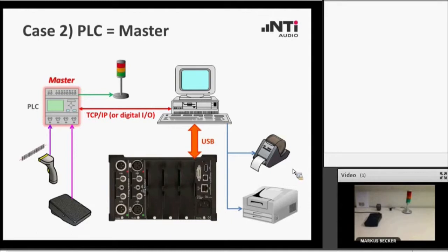The third option is to connect them directly to the auxiliary I/O interface of the FX100. And this applies not only for very simple devices like a foot switch or stack light; you may even connect a PLC to this auxiliary I/O interface and simplify your whole setup in this way.